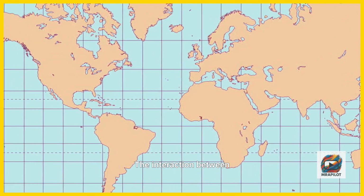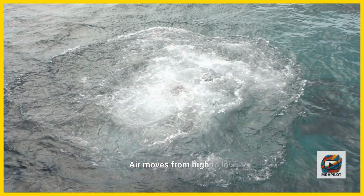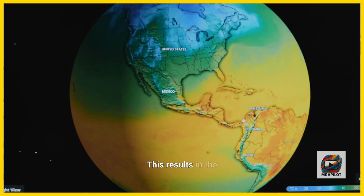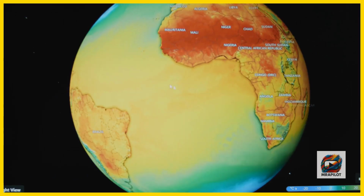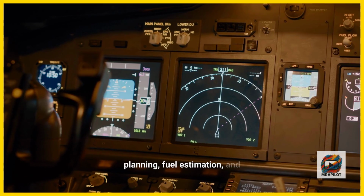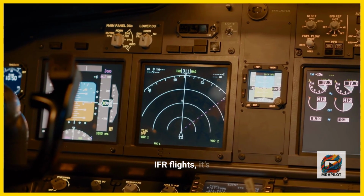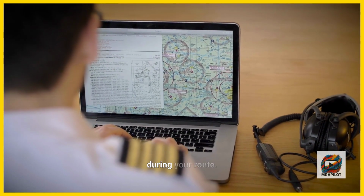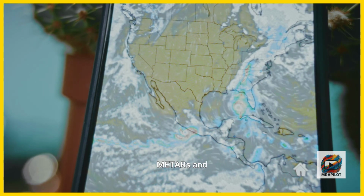The interaction between highs and lows creates wind flow across continents. Air moves from high to low pressure, but is deflected by the Coriolis effect. This results in the circulation patterns we see on global and regional weather maps. Understanding how these systems move helps with route planning, fuel estimation, and turbulence avoidance. For long-distance or IFR flights, it's crucial to check upper-level charts to see how pressure patterns will evolve during your route.